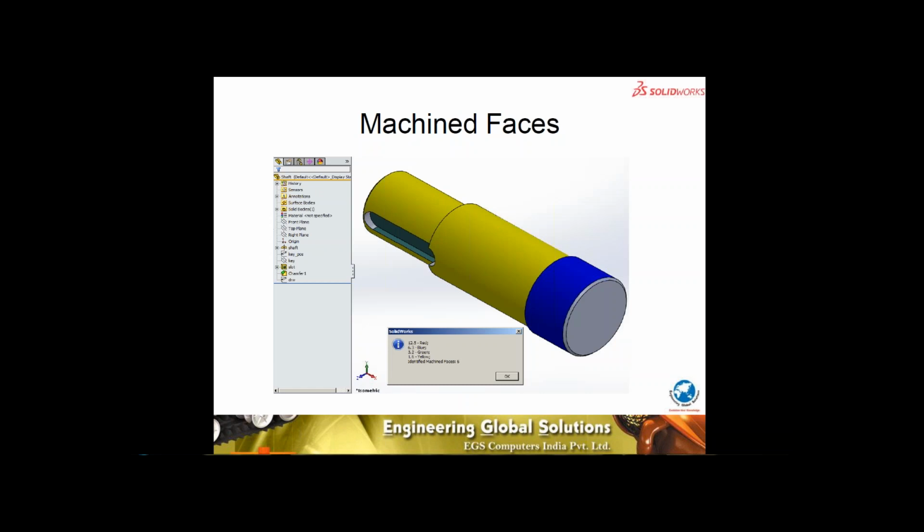In SolidWorks, with the help of a few macros, you will be able to represent the machined surfaces with different color coding according to the requirements of the organization, so that these don't get missed out and are a part of the checklist for the DFM process before the drawing sign-off happens. If it is there on the three-dimensional model, the annotations can be forced to come onto the two-dimensional drawing. As the part evolves, the drawings get updated as well.